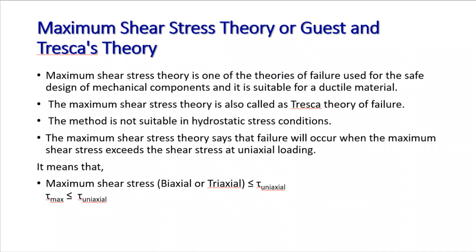They experience a certain portion of deviatoric stress and will fail under that. For that you can't apply every theory of brittle materials to ductile materials. For this purpose, we take shear stress as our component of interest and validate its applicability to the ductile material.